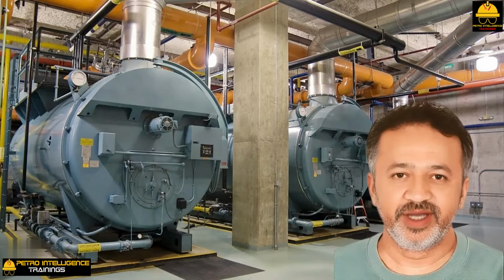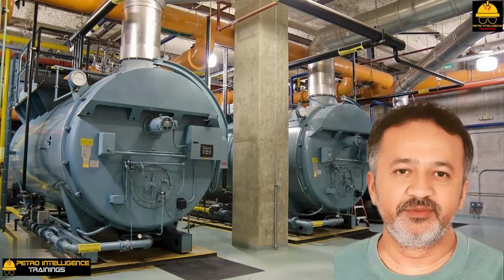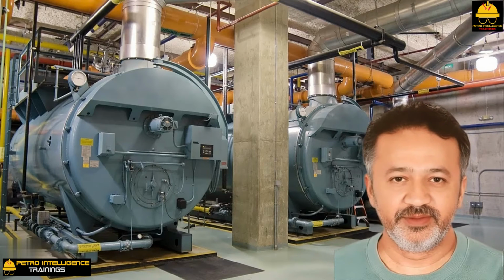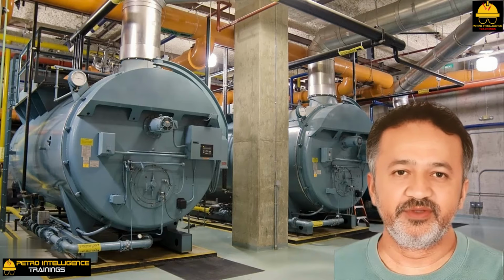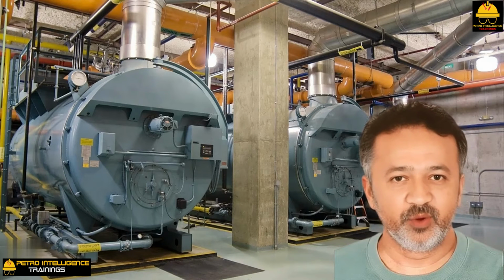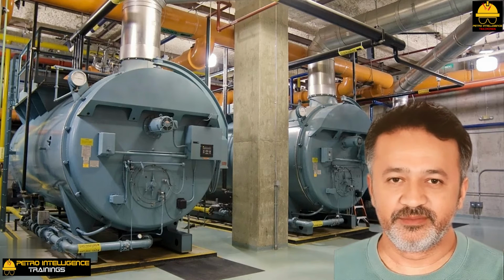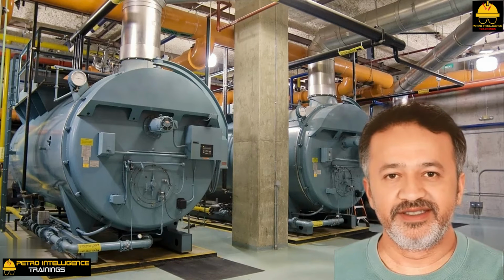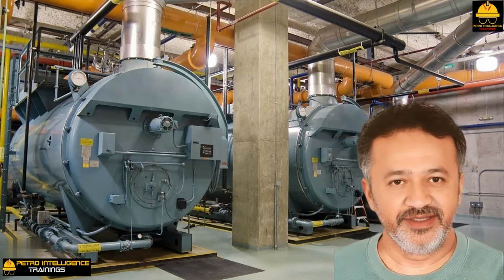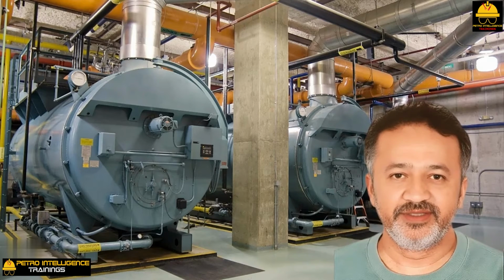Controlling steam drum levels. Ordinary level control does not work in steam drums or kettle boilers. The problem is the lower density of the boiling water as compared to the greater density of the non-boiling hot water in the external level sensing chamber. The boiling water will be at a 10 to 50% higher level inside the steam drum than the water in the level sensing chamber or gauge glass.